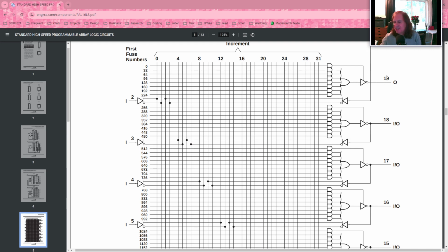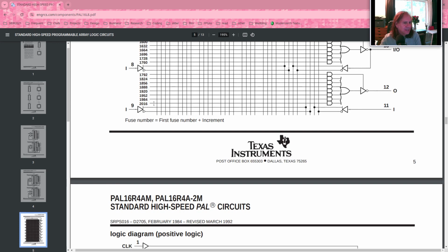And so pin 19 is not connected to anything effectively inside the chip. So we can use some of these pins as pure inputs by not driving a voltage onto that pin, by turning off these tri-state outputs. So this is a complex device, right?